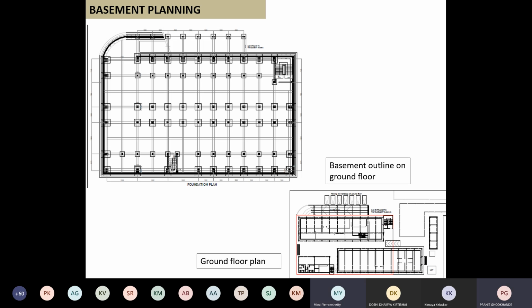Okay, fine. And ideally, I will not want them one above the other. Ask why? It will reduce the height of the basement. Because already, guys, this is the basement. It's the lowest part. That means it will have the thickest of the beams.